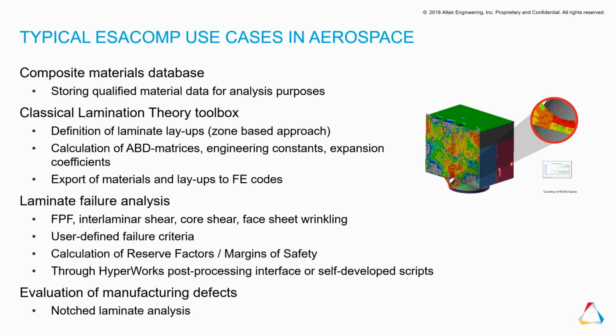One way of using ESAComp might also be not in the standard design process, but for instance when one needs to get a quick answer for the effect of a manufacturing defect, and so the notched laminate analysis we know is being used by some of our customers for that purpose.